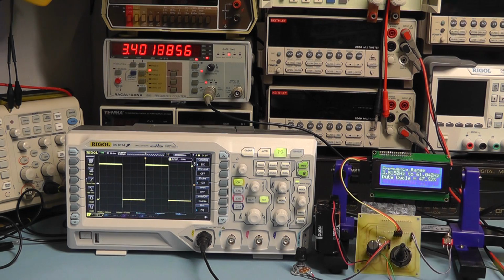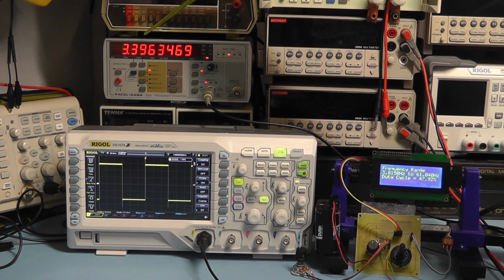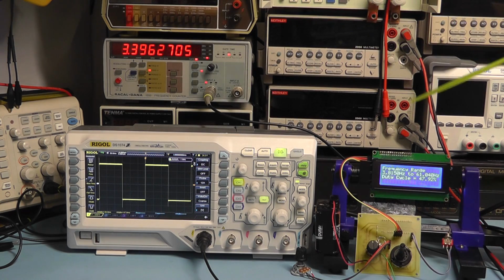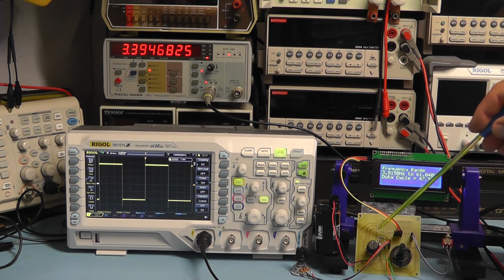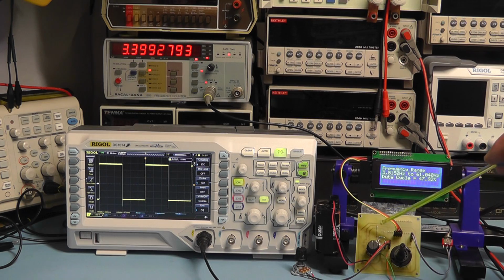That's right. So I've got the control turned to minimum, and we're reading a frequency there of 3.4, or 3.39 Hertz. According to the datasheet, we should be getting around 3.81 Hertz at that bottom end, but we can probably trim that with the padding resistors on the frequency control. There's the clean square wave you'll see there,